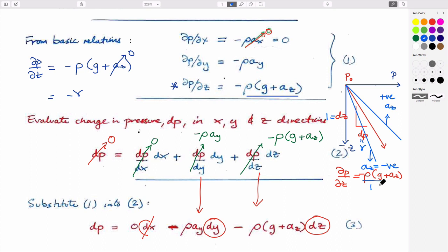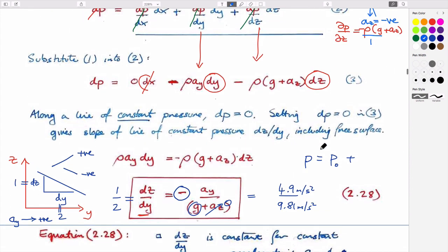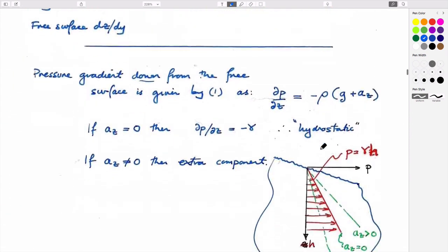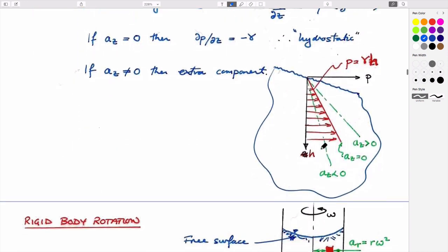And of course, if you're unfortunate to be in a plane accelerating downwards faster than gravity, it means you have an engine on the top pushing you down, then you'd actually have a pressure distribution within the fluid which would be negative. It would get less pressure as you get deeper and deeper in the fluid, and the fluid is being pushed to the back. And so those are the mechanisms by which we can evaluate that. And so that's, I guess, talked about here.